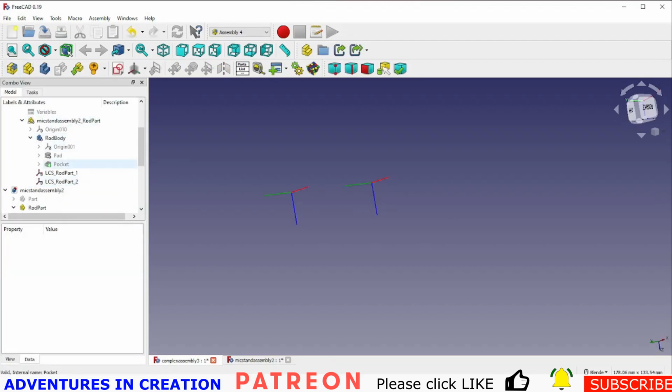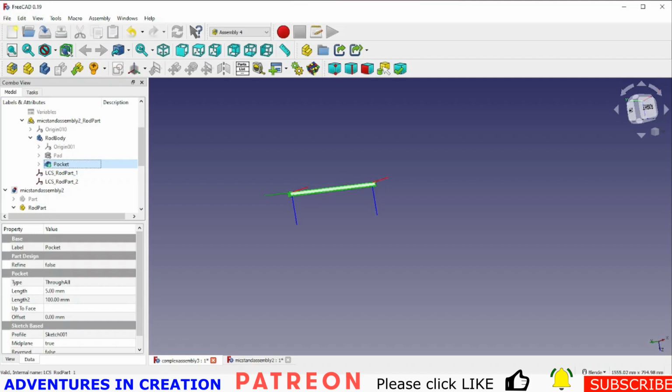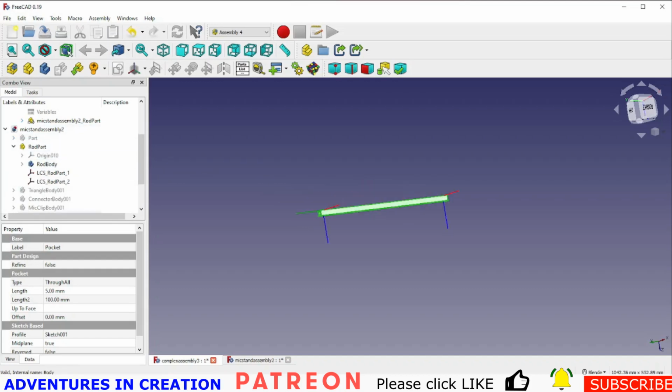To make it visible, we just have to get to that pocket and hit that, because the pocket was actually switched off when I imported it. If that's the case, you just have to work your way through the tree till you find the part that's switched off.